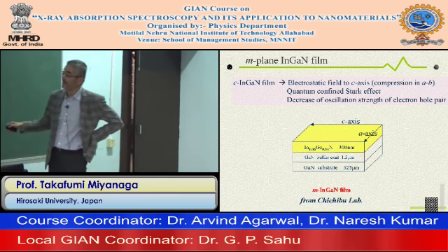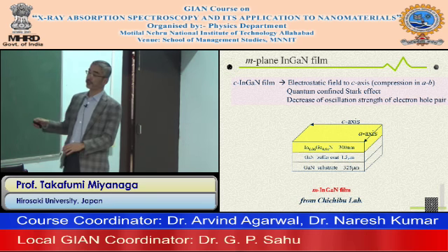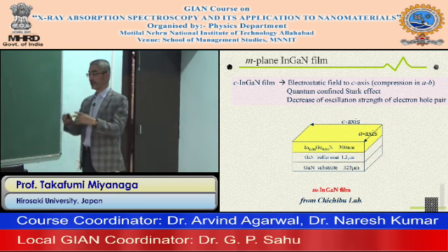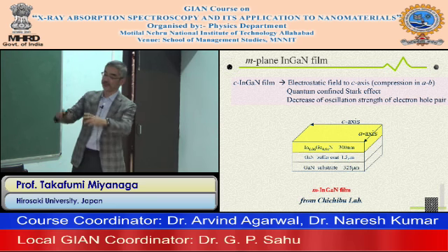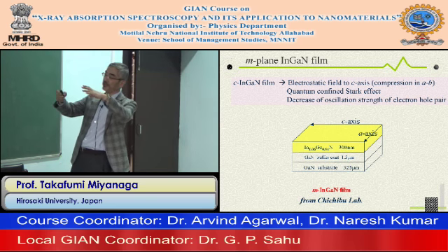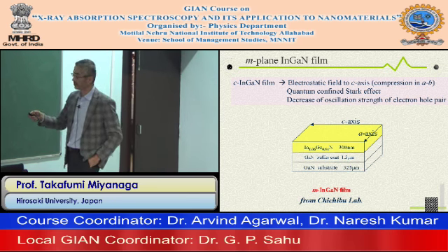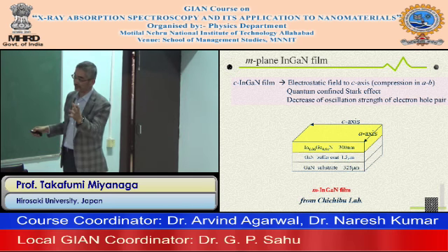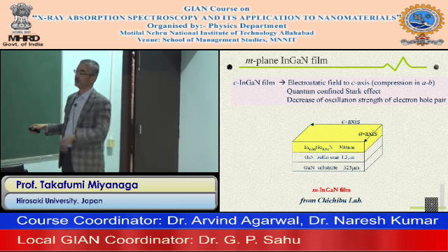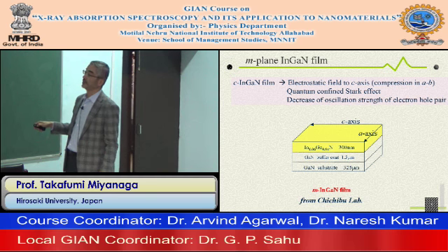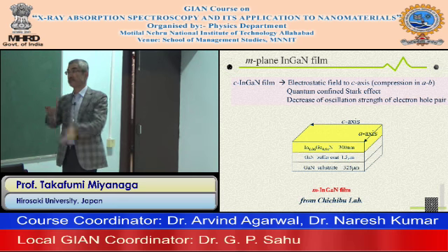First, we make a gallium nitride substrate and cut it. Usually, atoms are produced along the C-axis like that. After that, we cut the M planes very sharply. In the next steps, these indium gallium nitrides, this buffer and samples are produced on the M planes.